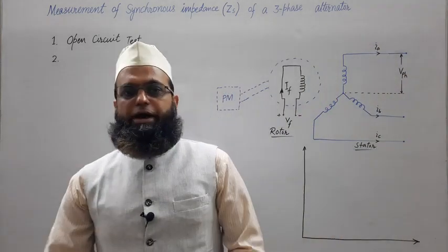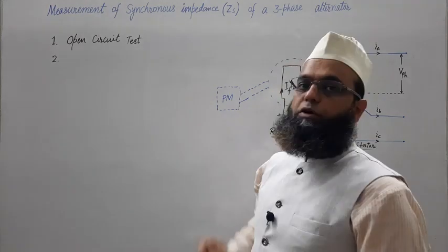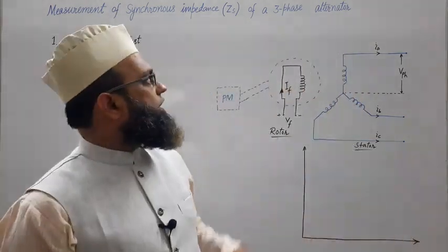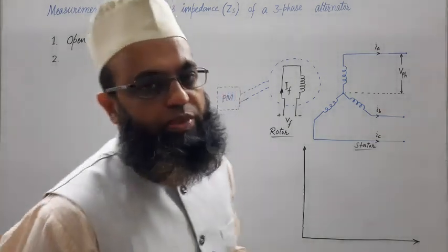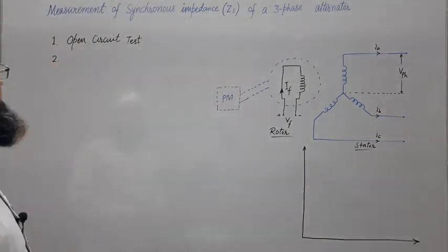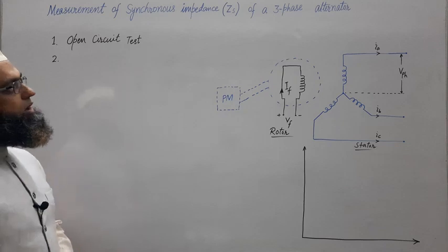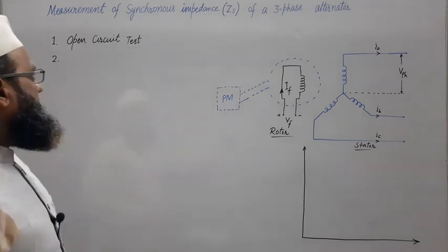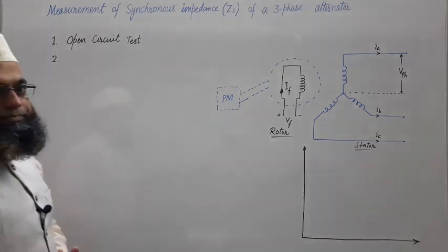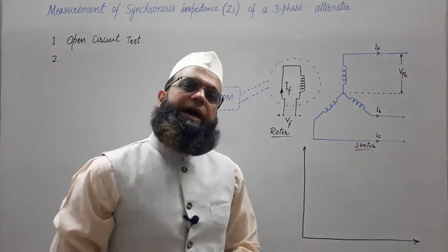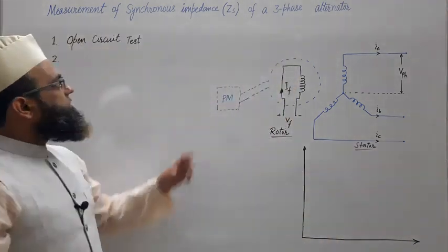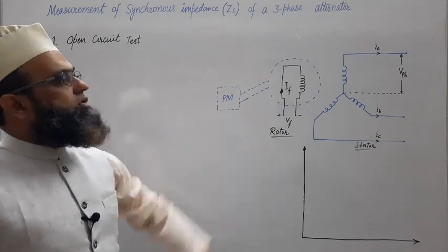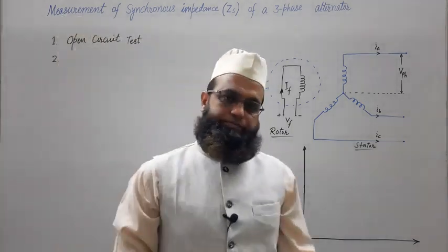Dear students, today I am going to discuss measurement of synchronous impedance of a three-phase alternator. For this, we need to perform open circuit test and short circuit test on the three-phase alternator, and with the help of these two readings, we will evaluate the synchronous impedance of the three-phase alternator.